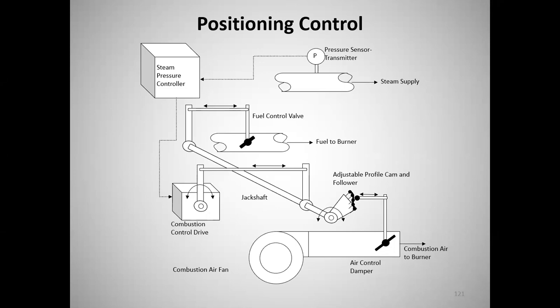And so if you're going to run in a climate like ours, if you're going to run a boiler like this, it needs to get tuned at least twice a year, going into the winter months and then coming out of the winter months, going into the summer months when it's warmed up, in order to be able to halfway control this oxygen content or the excess air going in. So these things are cheap. It's what comes on the inexpensive boiler. You buy the cheap control system. This is what you get, and you pay an efficiency penalty for it.